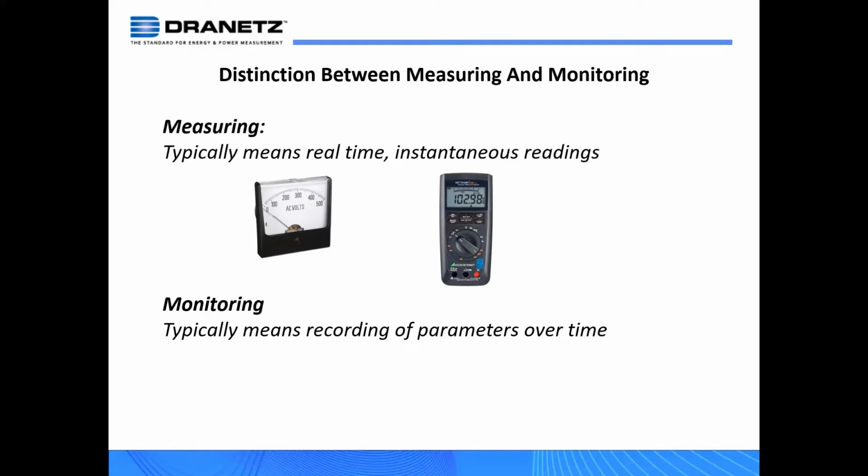A typical example is that I want to see what the building energy usage is over a 30-day period, which is the typical billing cycle. And so I would have the instrumentation that is suited to do that. So again, the takeaway from this slide: you have measurement, which is basically a real-time instantaneous reading, versus monitoring, which typically means recording of any power parameter over a period of time.